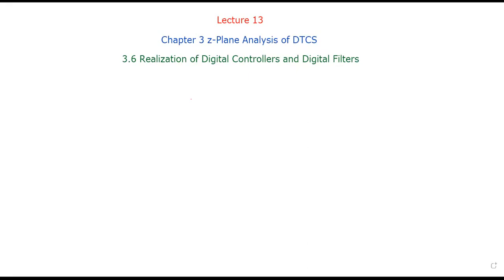If you implement the pulse transfer function as it is, then it is known as digital direct programming with n plus m number of delay elements.